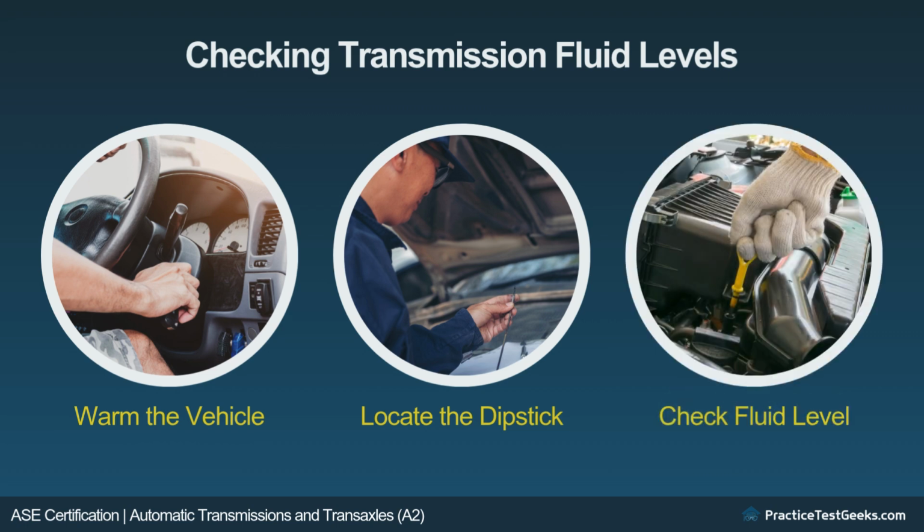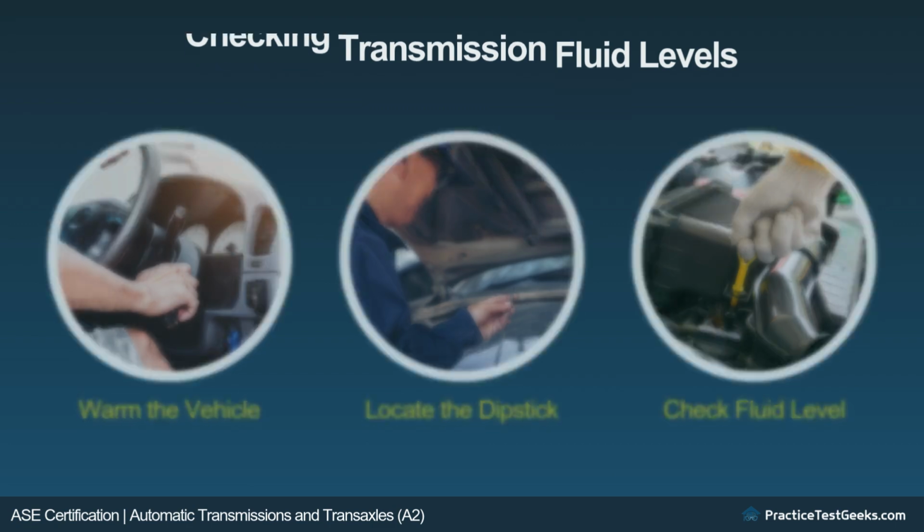Check fluid level. Remove the dipstick, wipe it clean, and reinsert it fully. Remove it again to check the fluid level. The fluid level should be within the full range marked on the dipstick. Tip: if the level is low, add the manufacturer recommended fluid to the correct level.